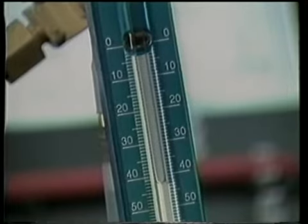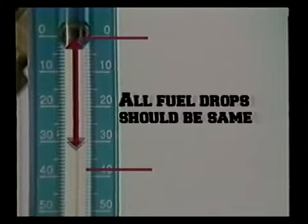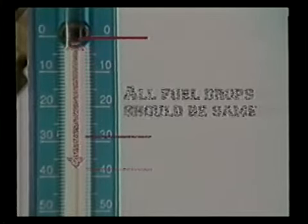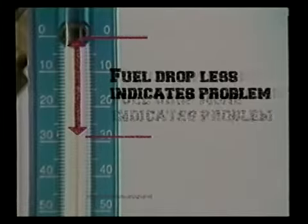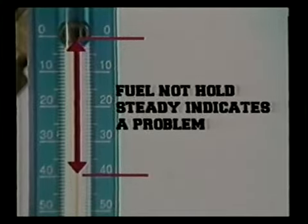All fuel drops on the sight glass should be the same as you test each injector. A typical variance might be 10% from one injector to the next. Less drop might indicate a plugged or restricted injector. Excess fuel drop might mean a sticking or clogged injector. If the fuel does not hold steady, other problems are indicated.